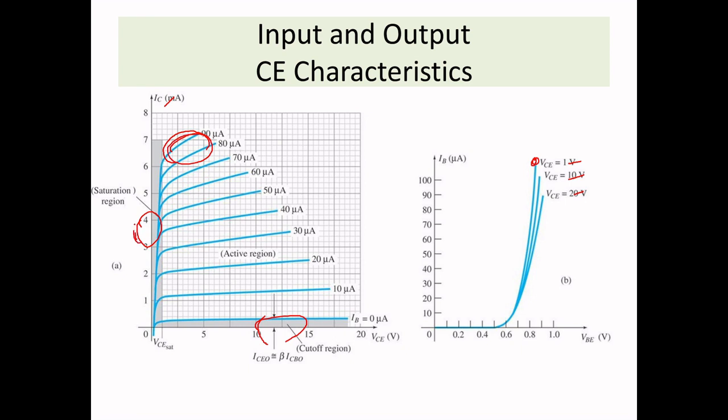So linear saturation region. See, this is only for a very small amount of voltage where it will be in forward bias for both the junctions. In this section only, your emitter base and collector base both will be forward biased. In this section, collector base and emitter base will both be reverse biased, and the current we can see is very less, something like microamps. So that's why it is highlighted in the gray color you can see here.